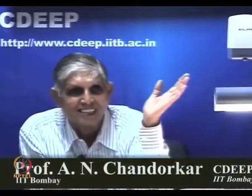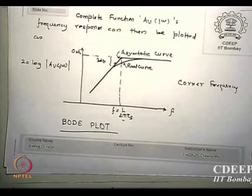Because in real life I want to know what is the frequency up to which I should not use the gain, or beyond which I should use it, or vice versa. I only want that value. The actual magnitude may be 3 dB, who cares? I want that frequency, is that correct? And I will always be away from those corner frequencies, to be guaranteed on this side or on this side. That is why these plots were called Bode plots. So in future we may not draw the actual curves, we may draw always Bode plots.